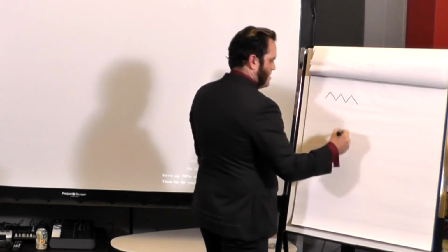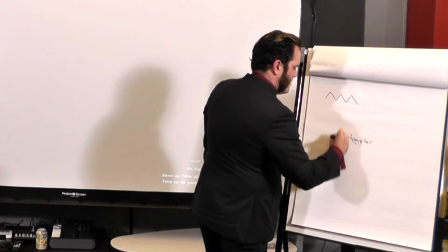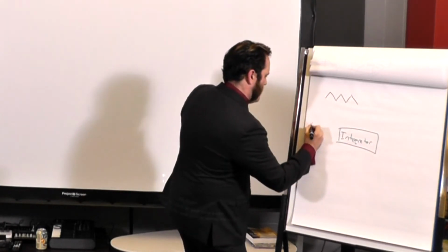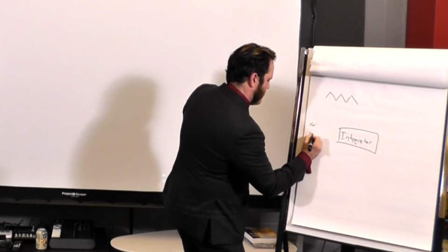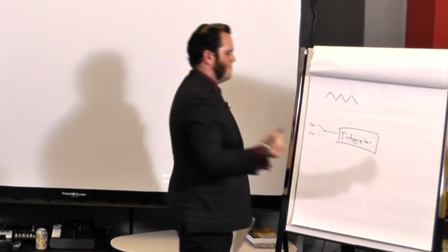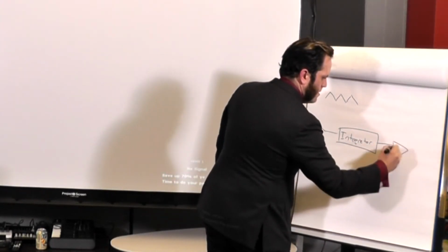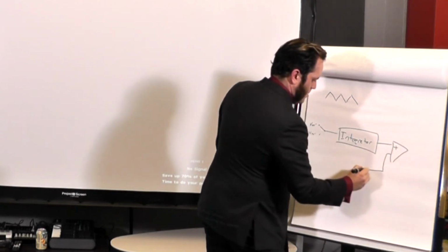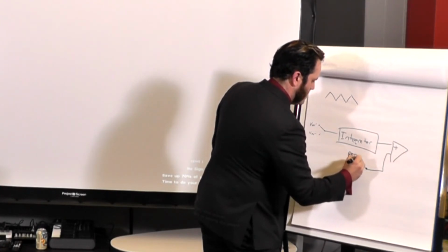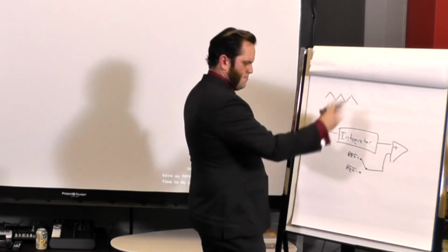All right, so basic idea here. We're still going to use an integrator again because we've got these nice ramps that we like. But I want it to go up and then down, and then up and then down. So I'm actually going to have a positive V in and a negative V in, and I'm just going to put a little switch here and throw that into the integrator. And that's going to go, again, into a nice little comparator over here. But what I'm comparing against is also going to switch, to reference plus and reference minus. And so that's going to do its magic as well.